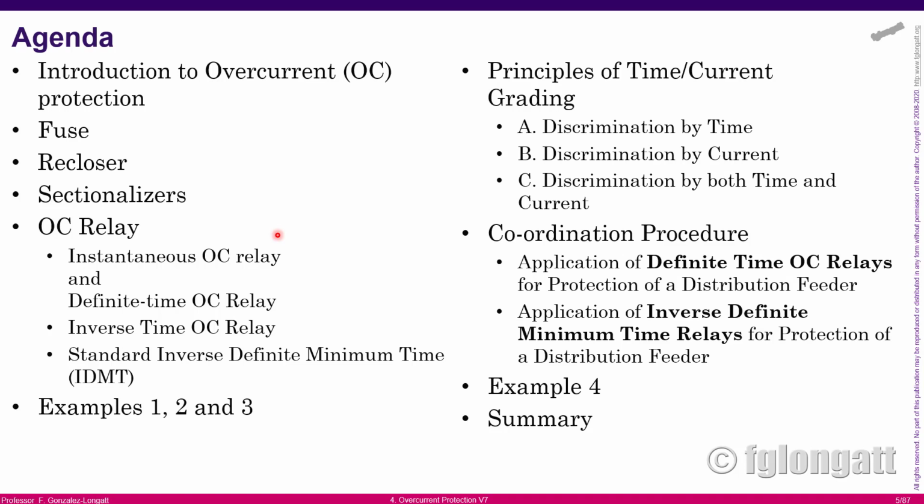I mean, when we are interested in identifying short circuit overcurrent faults, there are at least 3 techniques that we use for grading: discrimination by time, discrimination by current, and the third one is the combination of time and current at the same time, okay? I will just present what the coordination procedure for overcurrent functionality is. However, you will realize that it is a very broad and very complex topic, okay?